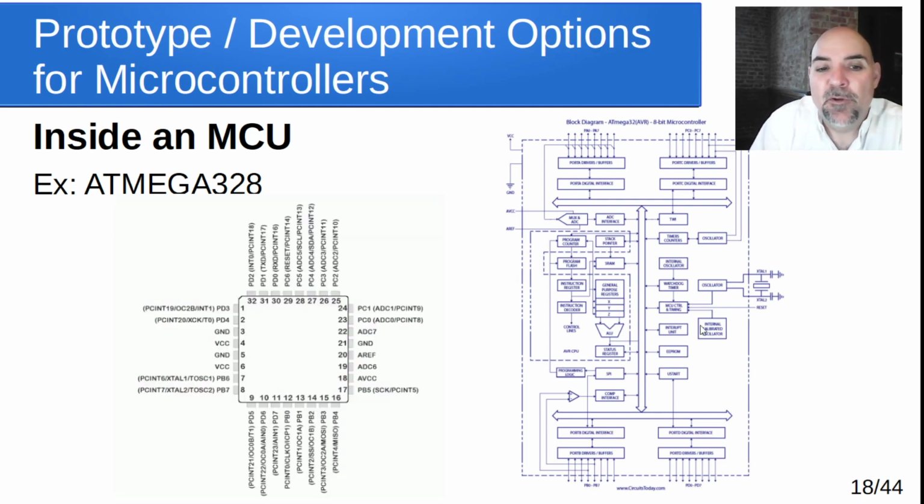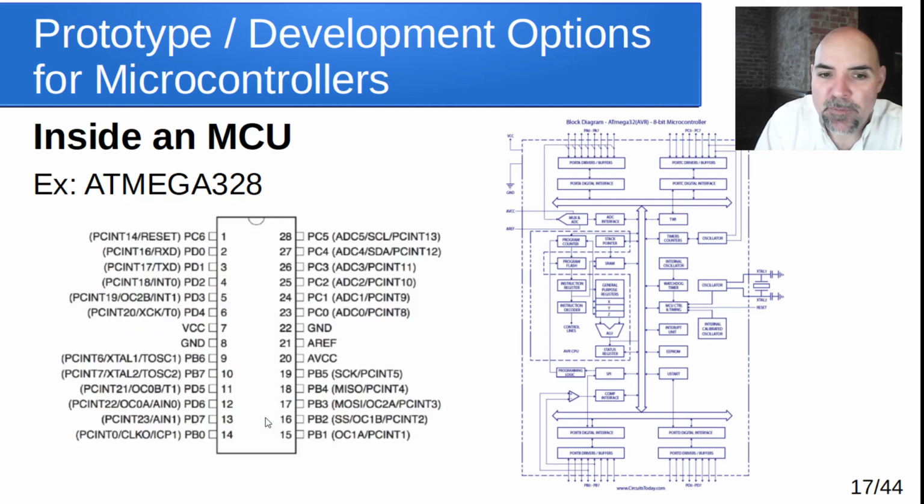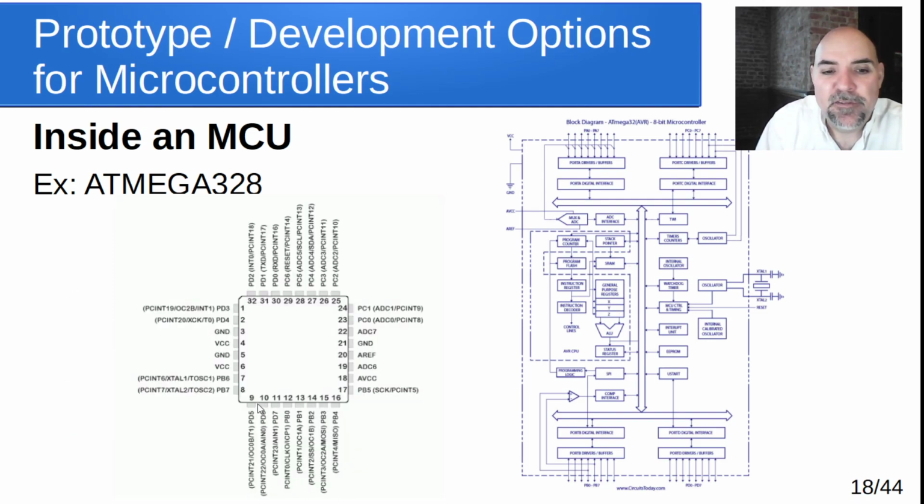All right, now this comes in multiple packages. This one was the DIP package. Notice you can also get that in a TQFP or a QFN package. So smaller form factor, but a little square with pins coming out 4 sides rather than being through-hole with pins coming out 2 sides. But notice it's the same parts that are in here.